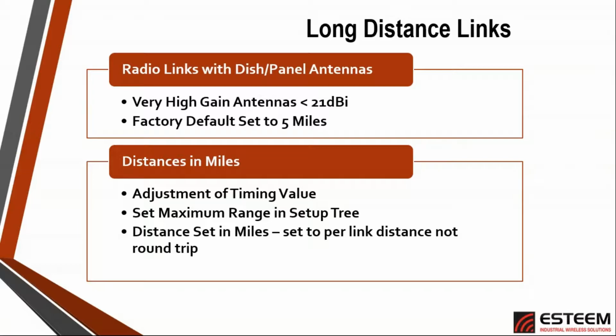Now that we're dealing with microseconds instead of milliseconds as far as timing, the radio really has to wait on the electromagnetic communication to go between two points, traveling at the speed of light. So there is a certain amount of delay for it to reach the remote and come back.